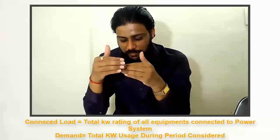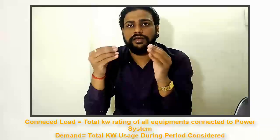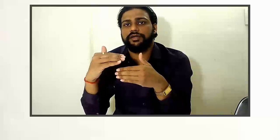Again, my demand is how much kilowatt is being drawn. Suppose my total connected load is 2000 watts in a simple house case, but it's not possible to draw everything. Sometimes I would have only one AC on while the other is not, only one television on or two fans on. So in such a scenario, my load will be varying. My total possible load was 2000 watts, but it will keep varying during the day around an average point like 1000, and my peak could be something like 1500. It could come in the afternoon while it is hot and both the ACs are on.